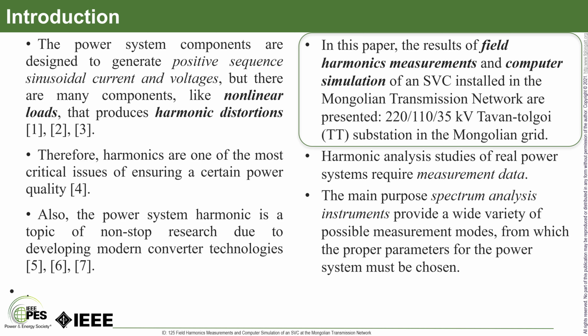At the same time, some harmonic distortions have the capability of affecting the lifespan of the equipment, which is the very specific case of transformers and some other devices. Also, power harmonics is a very interesting and hot topic in recent times, especially because of the development of modern converter technologies.